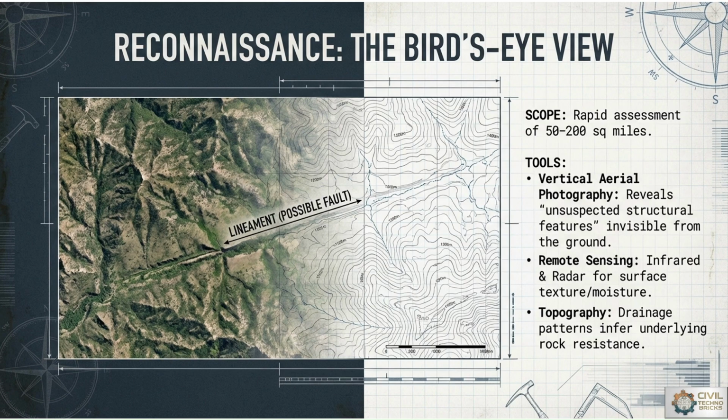With reference to topography, we can check the drainage patterns, that is valley lines and ridge lines, so that the impact of rainfall or the impact of the valleys and its necessity from the road construction or tunnel construction point of view. Means the reconnaissance survey is nothing but the bird's eye view. We can check the topography with reference to the bird's eye by the use of aerial photogrammetry tool or remote sensing tool based on some contours, based on some geological subsurface exploration.